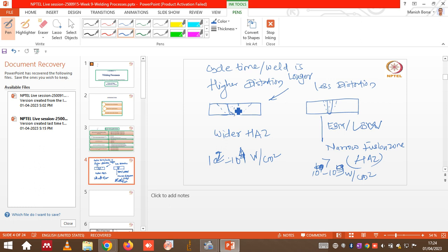Those particles act as nucleation sites, so during solidification of the weld zone we can expect heterogeneous nucleation and a very fine grain size. But the regions surrounding the fusion zone are only affected by heat, with no external addition of material, so their properties can't be modified later.